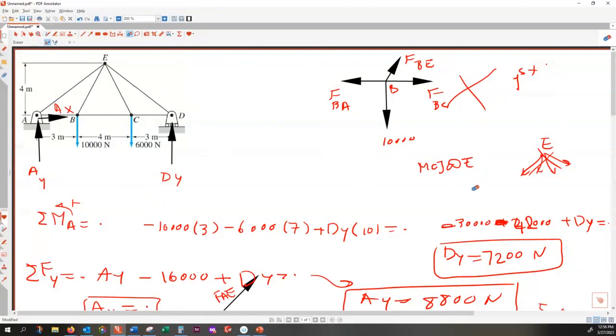All right. FBA is equal to FAB, which is equal to 6,600, and this is in tension, right? And here I have only two unknowns. So therefore, at this stage, you remember we postponed this step after reducing the number of unknowns. And now this free-body diagram can be solved because it only has two unknowns.